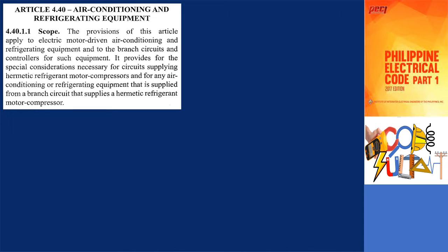How about for air conditioning unit? Article 4.40 of the Philippine Electrical Code applies to electrically driven air conditioning and refrigeration equipment. The rules in this article supplement or modify the rules in Article 4.30 and other relevant articles in the PEC.